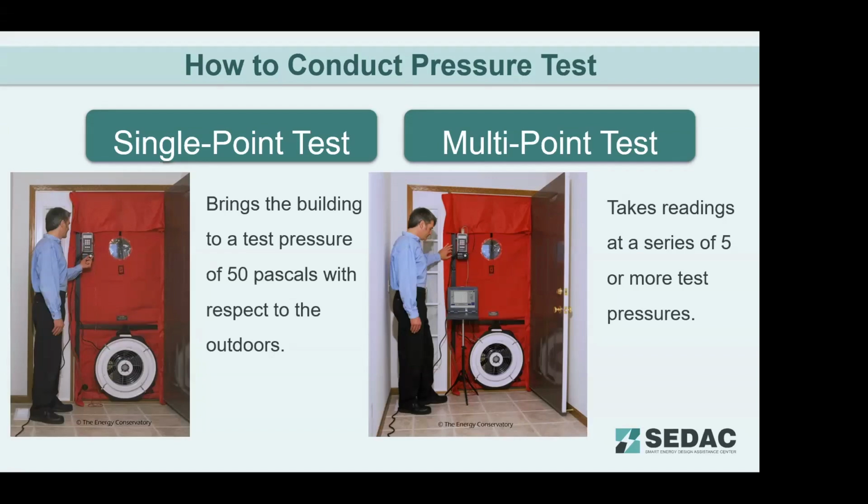If the single point test takes just a minute or two, the multi-point test might be 5 minutes. The only downside on the multi-point test is that if a contractor or a homeowner, whoever's building you're in, opens a door during the test, it might throw off your readings. So you really have to make sure everything stays sealed up during the period of time the test is running.